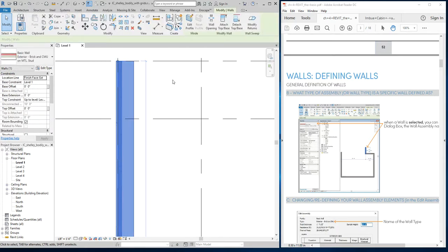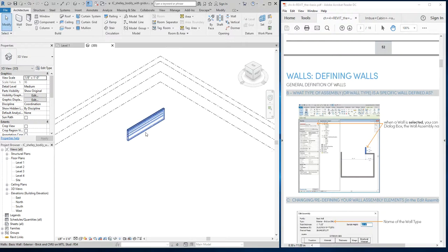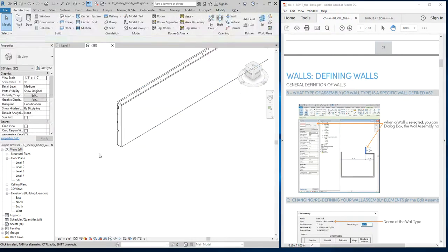And when I click on it, right, well, first thing, when I draw a wall and I don't define the top and bottom constraint, and I think Revit is remembering this from when we were drawing last time, usually it will define the base constraint as the level you're on, and then it will define the upper constraint as 20 feet tall, okay, unless you define it as a different height. I had just been drawing these walls defined to level 2 in our previous session, so Revit kind of remembered that.